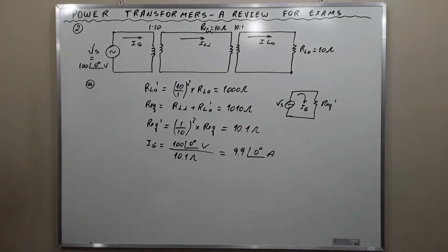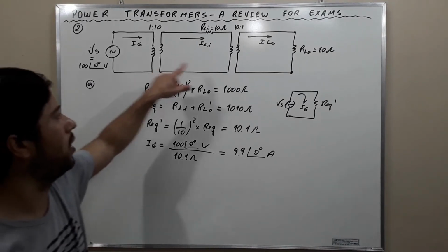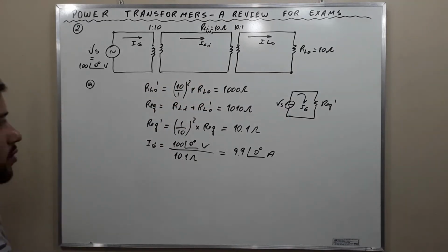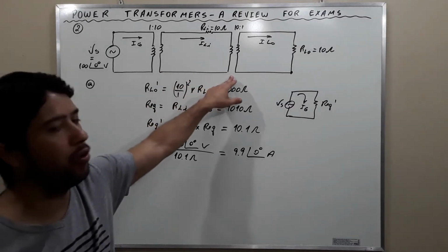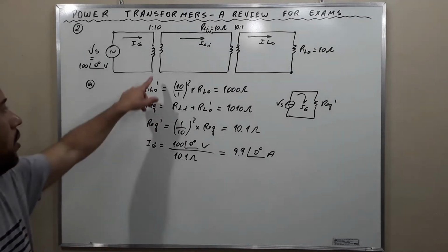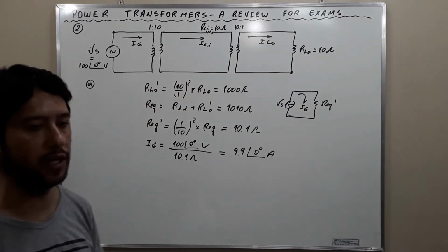But observe that these are identical ideal transformers. Whenever speaking about ideal transformers, we do not care about the losses within the machines. Only when dealing with real transformers do we compute and account for the losses in the machines.